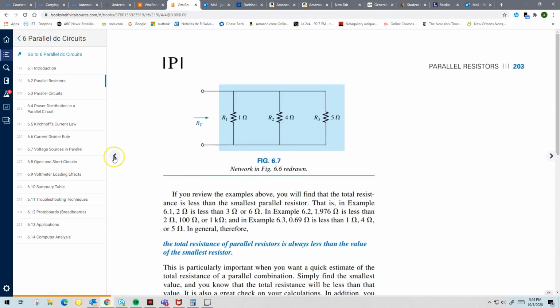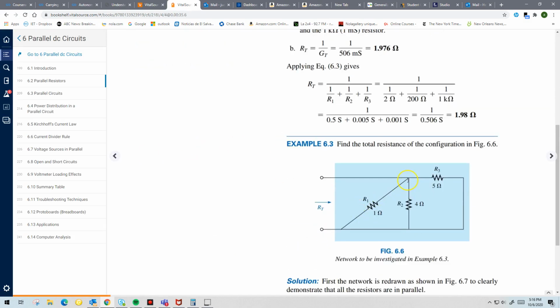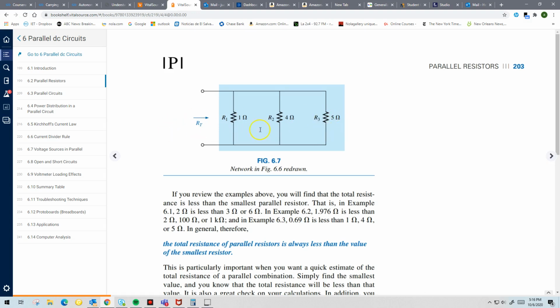And as you can see, if you redraw that circuit, in other words, if you move this connection and make it parallel to this one, actually physically parallel, and then you move this resistance down to this side, you get this, right? It's the same connection. It's the same circuit. You didn't change the connecting point. You changed the way the circuit looks, right? But maybe this is a little more obvious for you. So don't be afraid to redraw the circuits as long as you keep the connections consistent, okay?